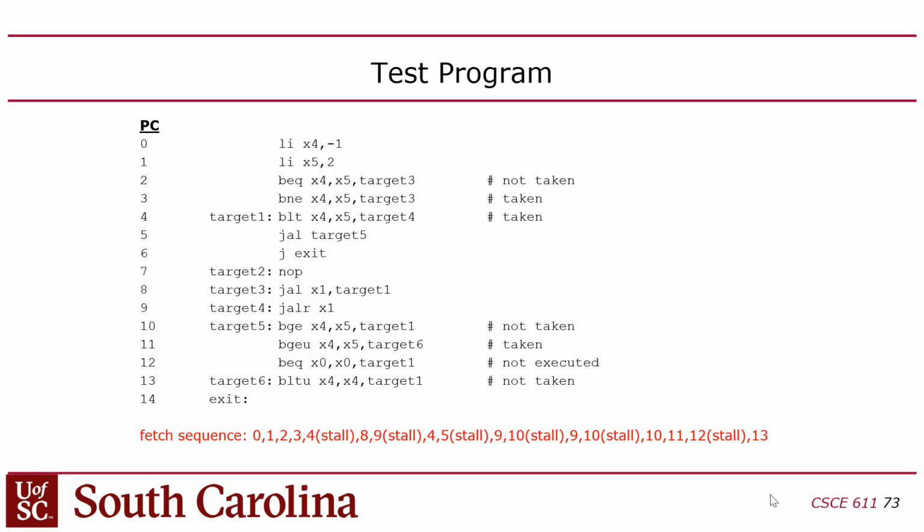Yeah, you just explain how you test it. So we're usually pretty vague about the testing, although obviously my position is you should be able to use this program to test it because this program tests every instruction. The problem though is it tests all the branch instructions, but it doesn't test both outcomes of all branches. So in that sense, it's not really a good test. But if your CPU gets through this, then I'm happy with that.